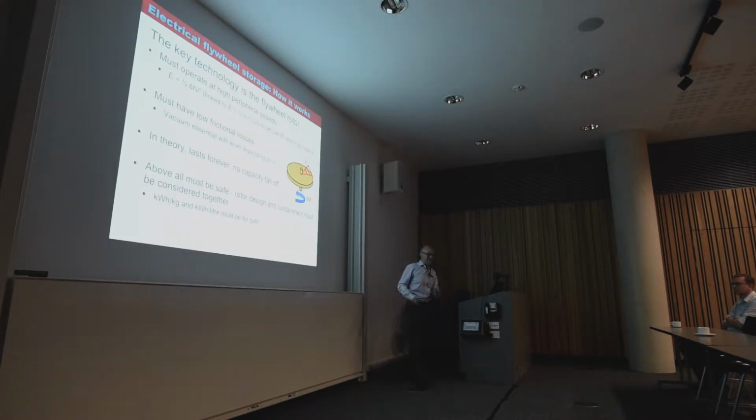And really, to make this machine feasible, viable, you've got to get the weight down. There were extremely heavy flywheels in Victorian times, which is what most people think of, in the Science Museum, but it'd actually be a very compact machine if you do it right. So you've got to get the velocity up. Half mv squared is related to half I omega squared, but in a rotor the velocity is proportional to the radius, so that's where your mass is and how fast you spin it. But basically you've got to spin it fast, which means high stresses.